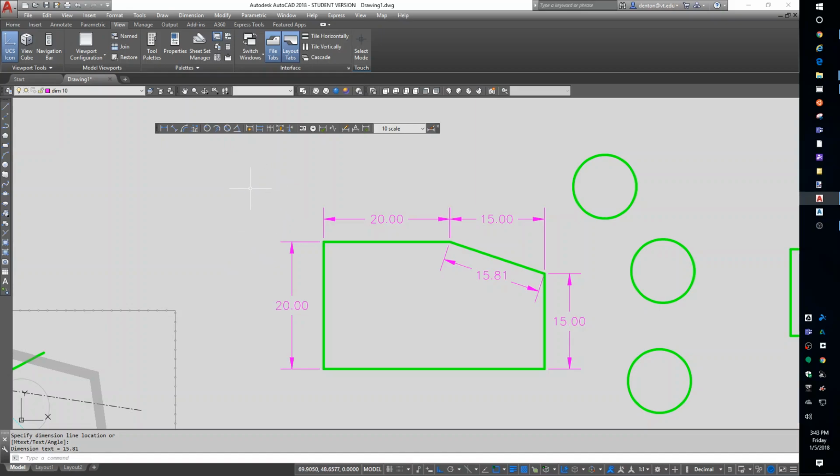But anyway, jumping into it, if I had an arc, the arc dimension would let you select the arc and label it. So it's giving you the arc length. If you do an angle and you click the arc, it's giving you the degrees of the arc. Also, with angle, you could grab two lines, and you could say, I want this dimension, or I want this dimension, or I want that dimension. So you can pick what you want to show. Okay, so that's an angular dimension.